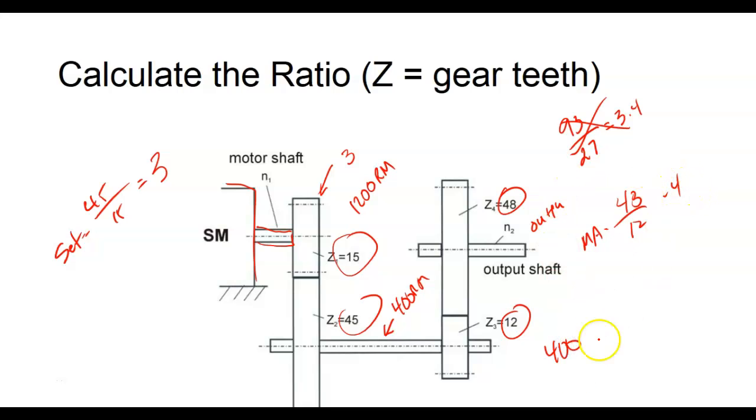And then we divide this by what? What's our mechanical advantage? 48 over 12, what's that? 4? So what's it going to be turning out here? Okay, 100. So I'm getting 100, up here. So this guy here would be turning at 100 revolutions per minute. Y'all understand how we did that? Yes or no?